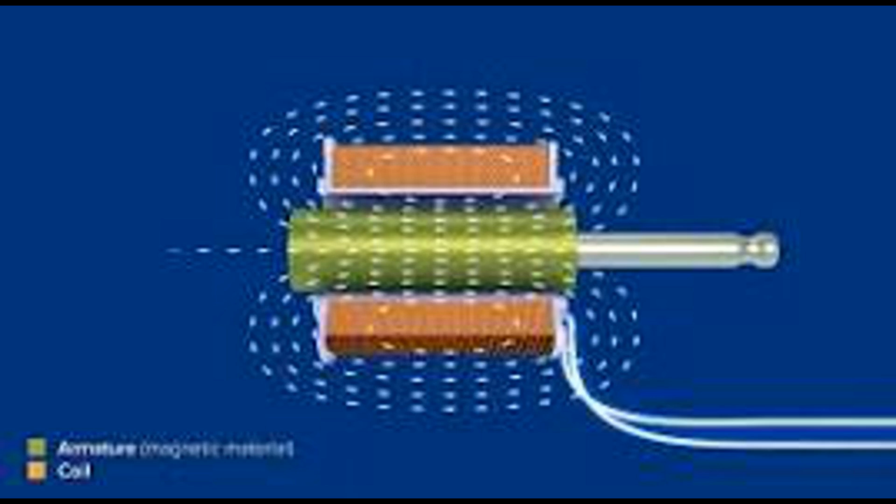Solenoid valves help control the flow of transmission fluid, enabling automatic gear shifts. Locking systems. Solenoids operate door and trunk locks in modern vehicles, enabling remote locking and unlocking. Anti-lock braking systems, ABS. Solenoids control hydraulic pressure in the braking system to prevent wheel lockup during braking.